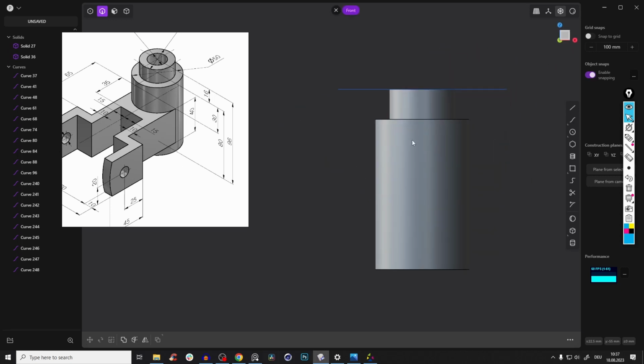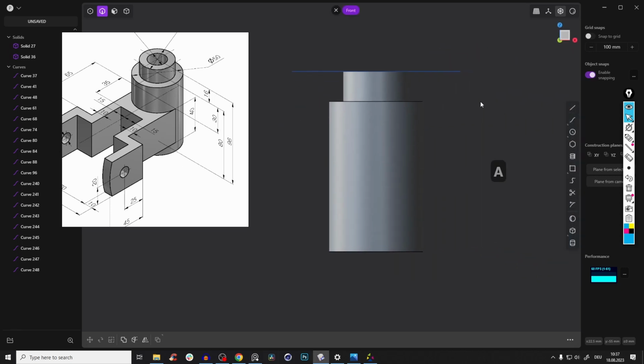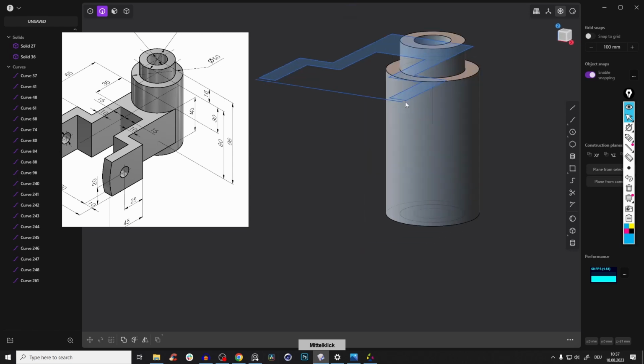So go to the front view and create the line, Shift A, snap it to the middle, and just drag that down with the value 30. So again, type in 30, right click, perfect. So now we know all of those edges, or the sketch, has to be at this endpoint. So very simple.